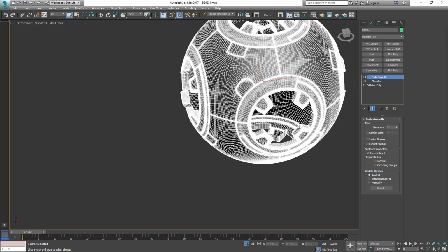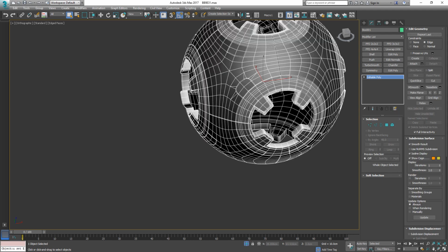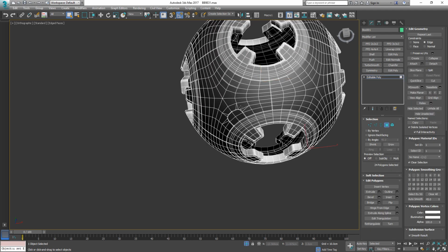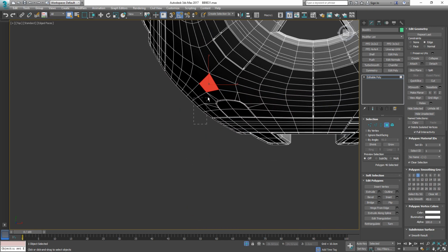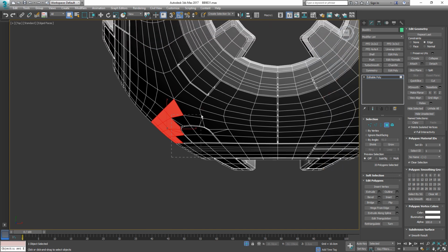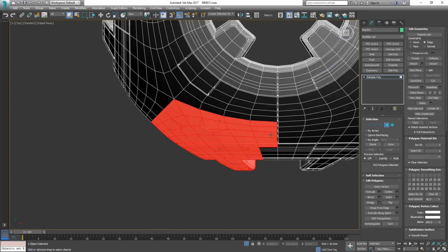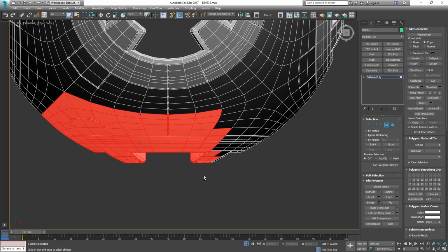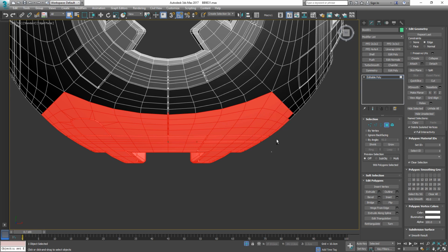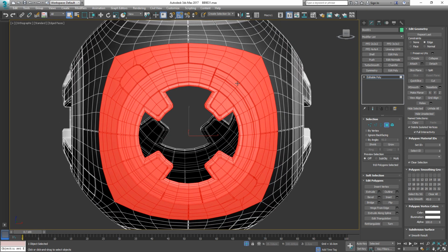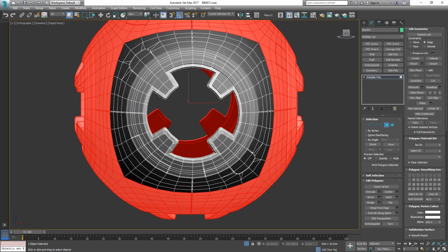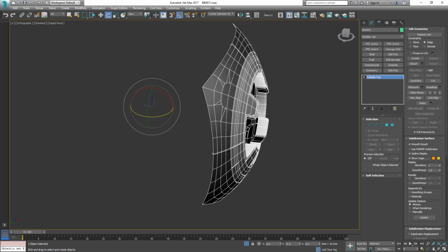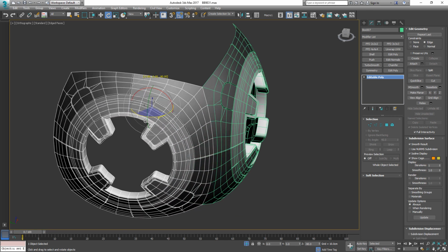So let's just take the modifiers once again here and cut them, because now what we have to do is go back into our polygon mode, and we want to copy that as we did before so that we have it on all sides with these details. So let's make a selection here once again. You're already familiar with that step from earlier. We're gonna select that, make sure we have exactly that here, and then Control and I and delete the other side that we don't need, or the other sides.